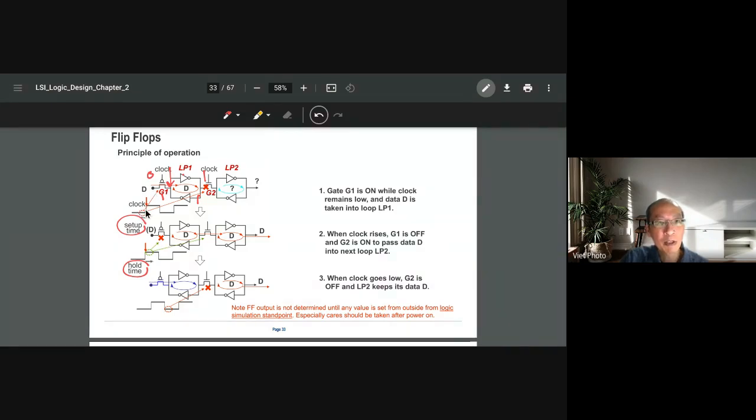Let's say I have a 0 here, and it's stable. Then when I turn the clock to 1 to cut it off, it knows that now it's gone, and I have the correct data here, right? The same thing applies to hold time: after the edge, the data needs to be held. You need to understand that setup time is before the clock, and hold time is after the clock.